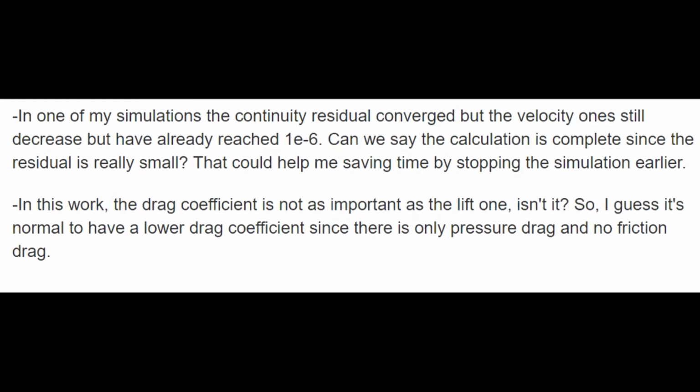It means that from one step to another step, you have a change of parameter smaller than 1/100 of percent, sorry. It's an infinitely small value of changes, and we consider that change does not happen anymore. So 10 minus 4 is already considered as converged.